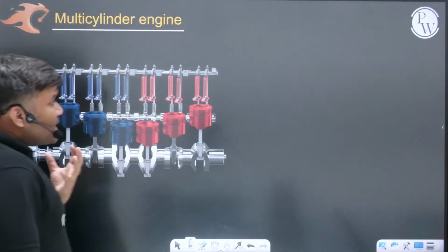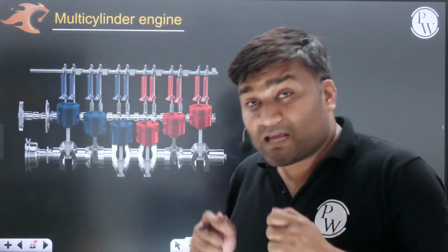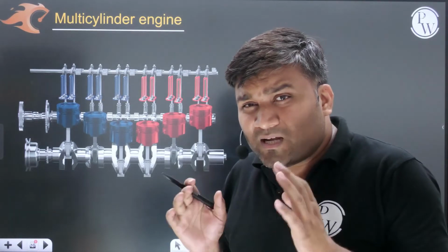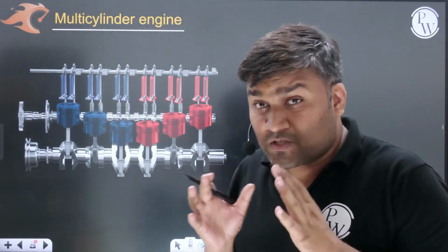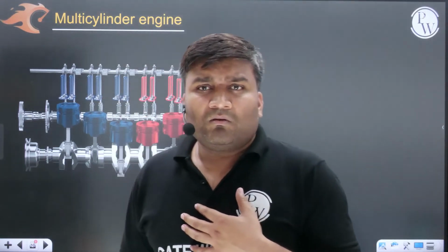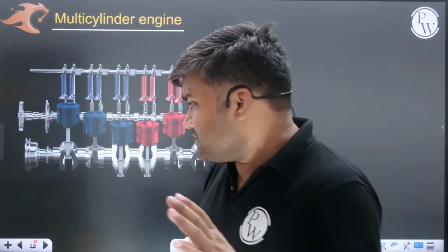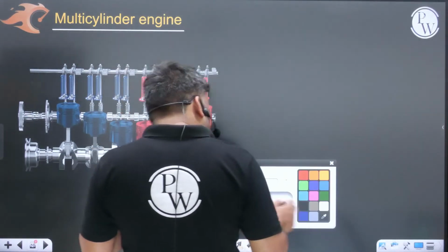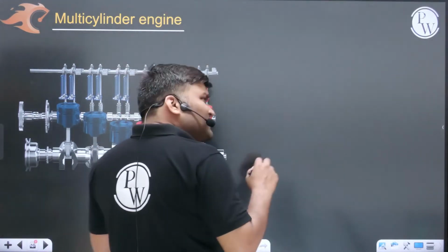Now, to reduce the requirement of the flywheel, or to make our flywheel lighter, the multi-cylinder engine concept was introduced in this world. Many people have this in mind that if I use a multi-cylinder engine, power increases, or they say that multi-cylinder engines were introduced to increase power. No. Simply, if you have to increase power, I have some other way.